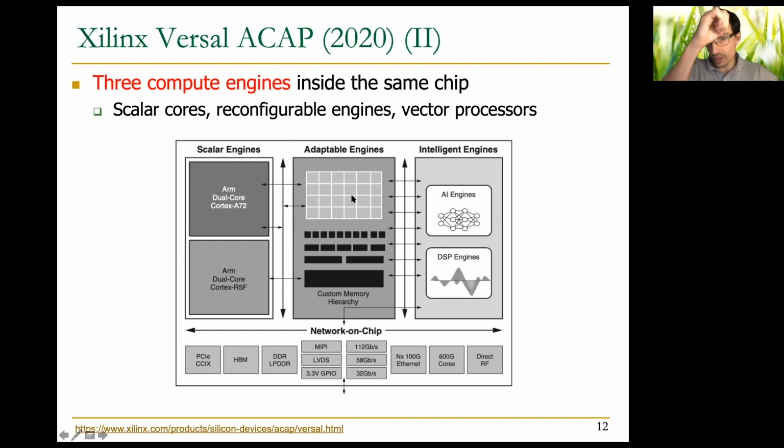Okay, there is a question. How does the chip decide which compute engines to use for each task? Is there an inference profiling mechanism to classify workload? This is a very good question. The first answer is that you will be the one who decides what's the right place to execute a particular operation, a particular kernel.